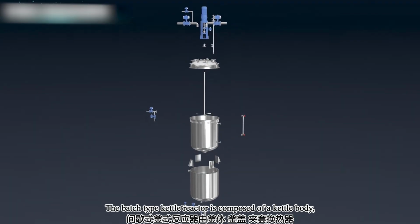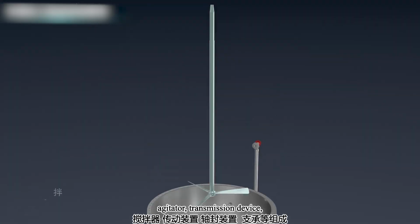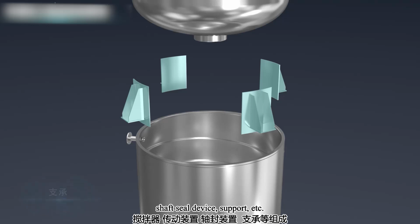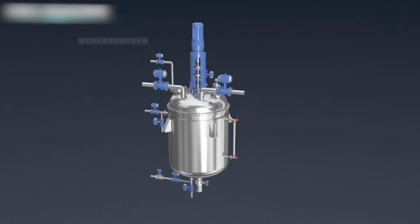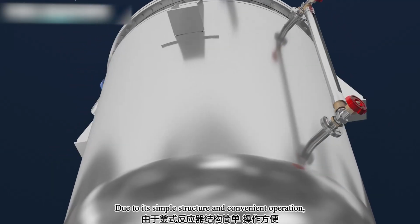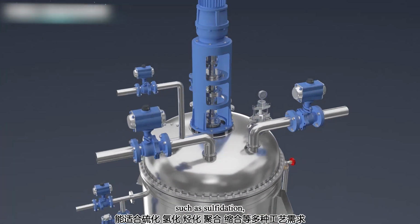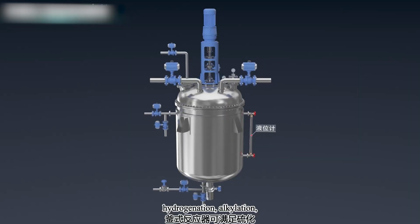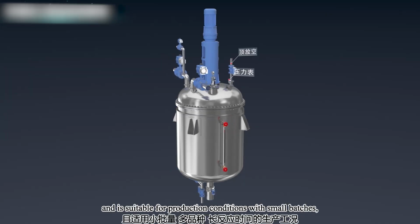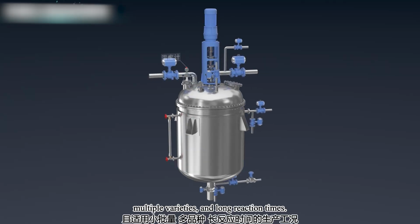The batch-type kettle reactor is composed of a kettle body, kettle cover, jacket heat exchanger, agitator, transmission device, shaft seal device, support, etc. Due to its simple structure and convenient operation, the kettle reactor can meet various process requirements such as sulfidation, hydrogenation, alkylation, polymerization, condensation, and so on, and is suitable for production conditions with small batches, multiple varieties, and long reaction times.